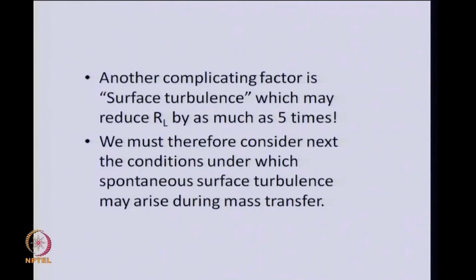There might be changes in density or temperature depending on what is the cause of stirring, how do you cause the mixing or agitation. All these complications will mean that now for all practical purposes you may not be able to deduce the liquid phase resistance from first principles. Each individual case will have to be dealt with separately.